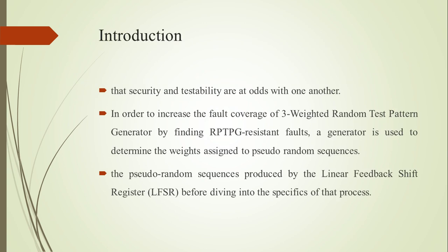So, the introduction of the project. In order to increase the fault coverage of weighted random test pattern generation by finding random pattern resistant faults, a generator is used to determine the weights assigned to pseudo-random sequences. The pseudo-random sequence is produced by the linear feedback shift register, LFSR.